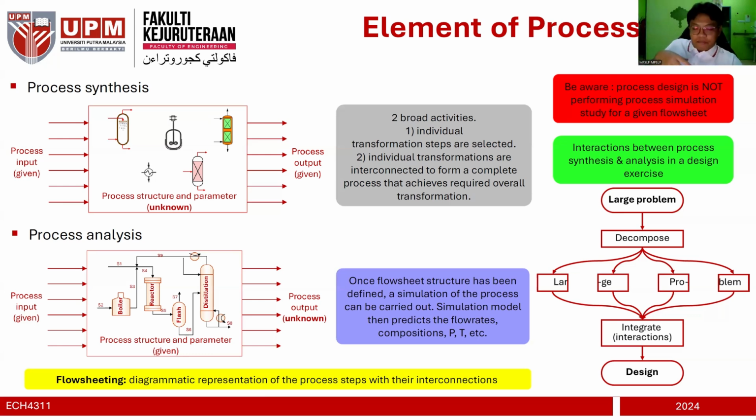But one of the issues when dealing with production of polyethylene and polypropylene is the buildup of ethane or propane, because these components have a single bond, so they cannot react to form polymers in polymerization. What they need is ethylene and propylene.